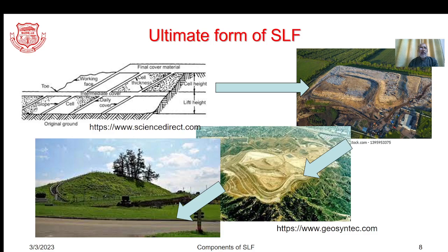So this is giving a fairly good idea of the various phases. This is indicating the bed preparation, placing the impermeable layer, placing the cells, going through the lift, providing the intermediate layers, creating the benches, laying the final cover. So at this stage the construction phase is complete.